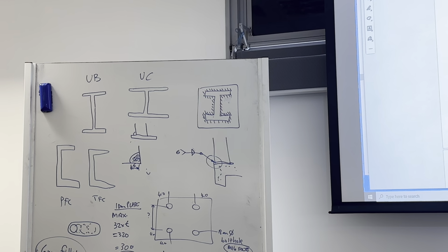There we are. There's a picture of welding 2 rods together. So what they do is they do a V cut, and then they put the weld into the V cut. Here's 2 rods coming at 90 degrees. And here's what I was talking about, how they weld a member coming down at 90 degrees to another steel member. There's a one-sided weld.